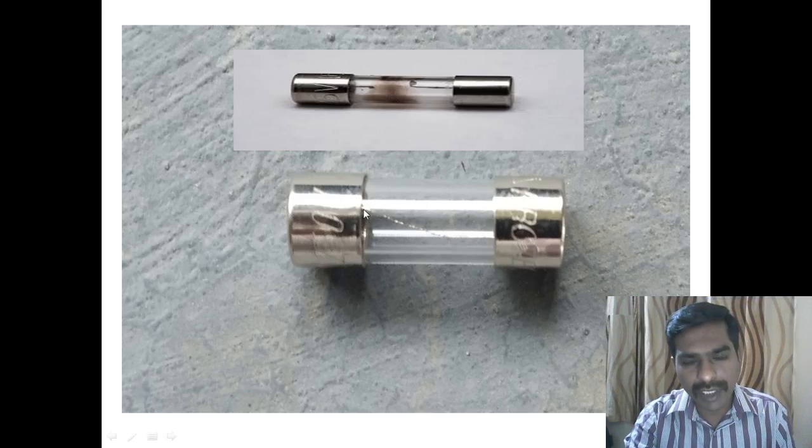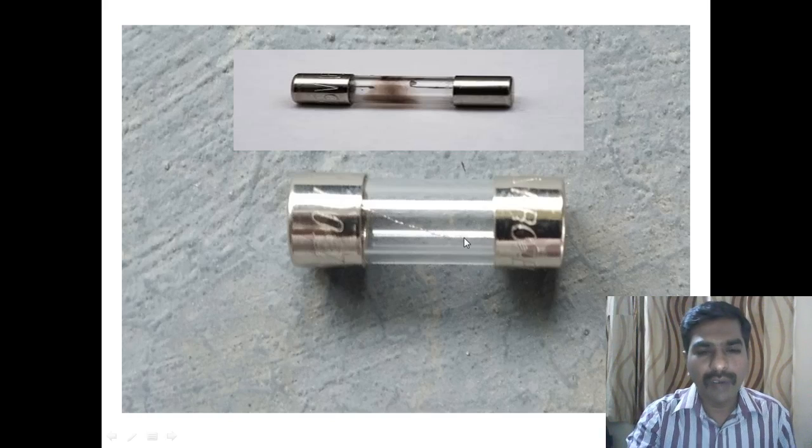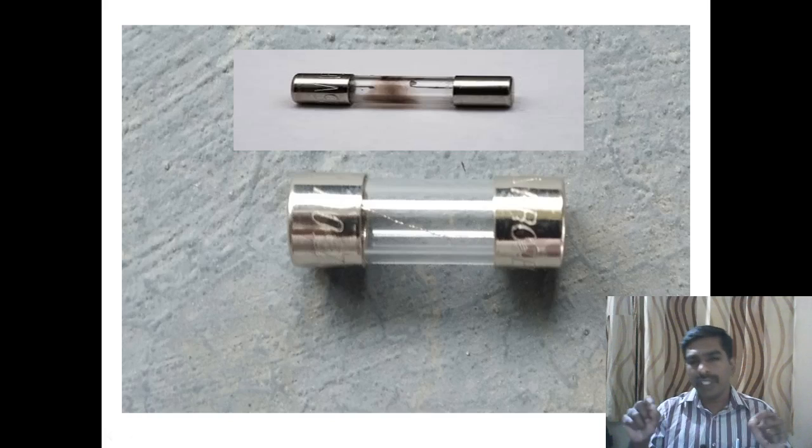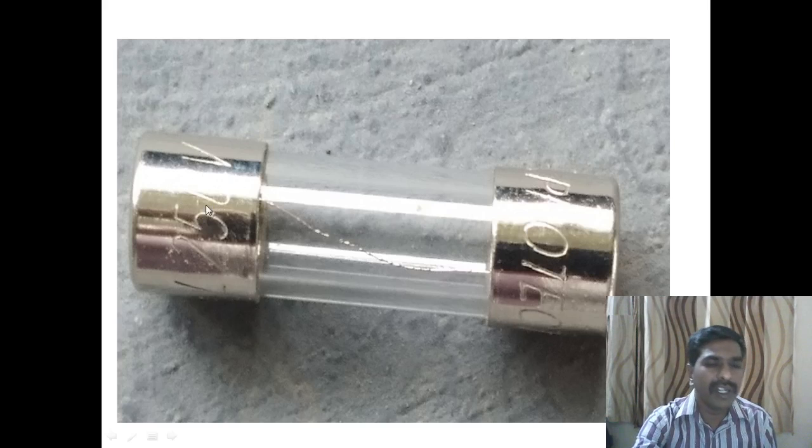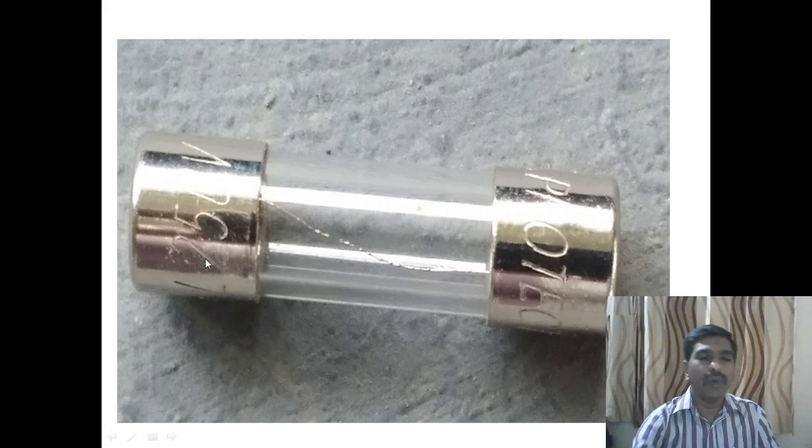The fuse consists of a single thin wire inside. You can observe this thin wire. Whenever a maximum current flows through that thin wire, since the wire has a low melting point, it will melt and break the circuit, and it protects against the maximum surge in current. So this is used as a protecting element, and this is an enlarged image. You can see the fuse has different current ratings, such as 100 milliamp, 500 milliamp, 1 amp, 2 amp. The current rating is mentioned on the fuse.